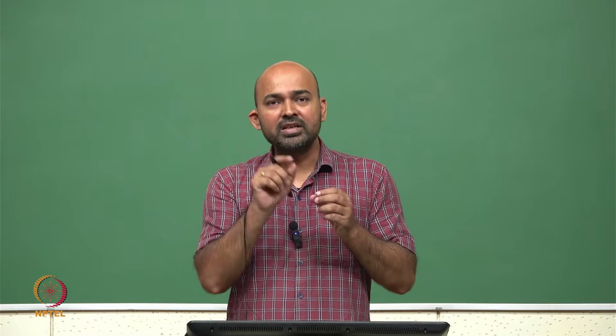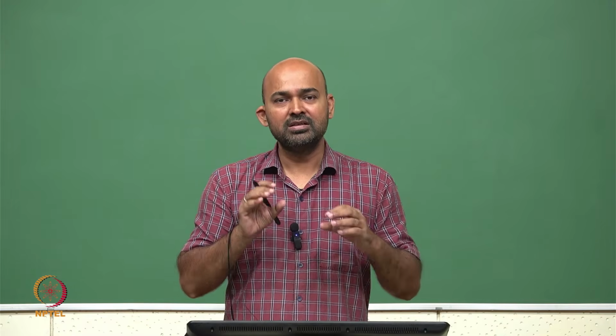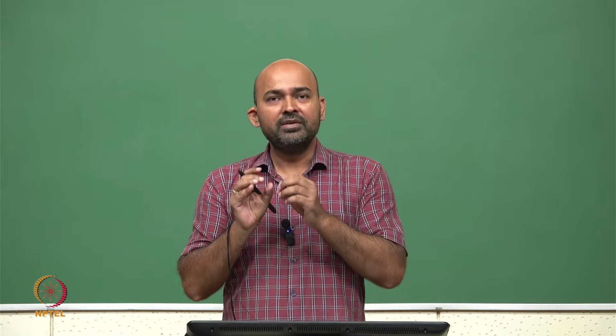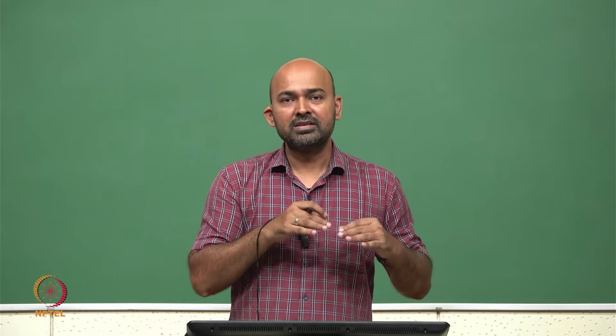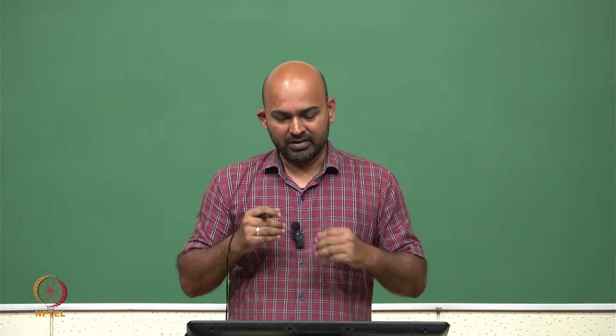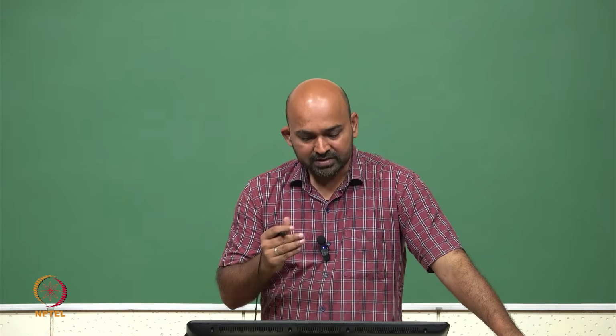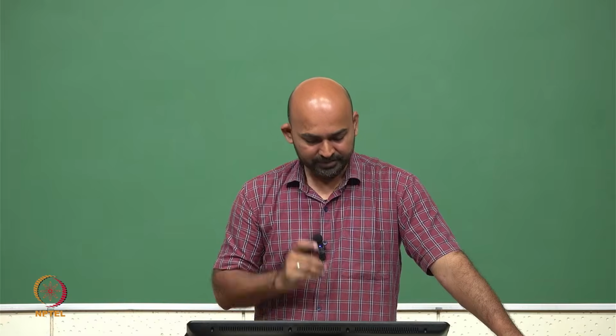It means their cross section area is very limited compared to the wire. So these contacts and vias offer higher resistance compared to the wire resistance. So we need to optimize this contact resistance as well. So these contacts and vias need to be considered very carefully.